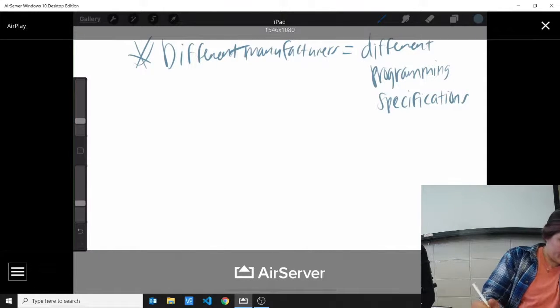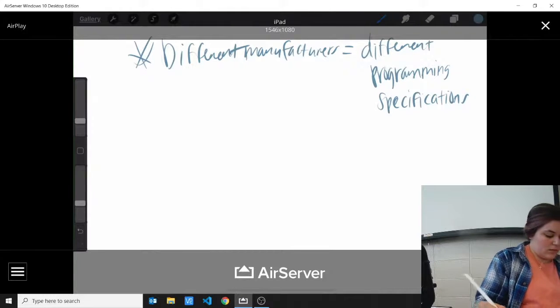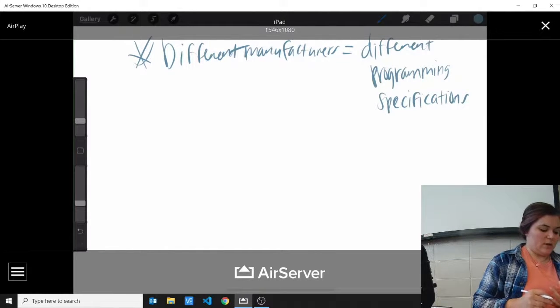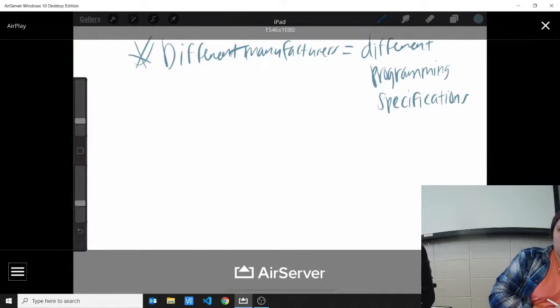Alright. Except for a few differences, programmable controller line diagrams are similar to standard hardware line diagrams. The line diagrams we've already seen in this class are basically the same thing. Their line diagrams have two vertical power lines that represent L1 and L2, except no voltage potential exists between the two lines.